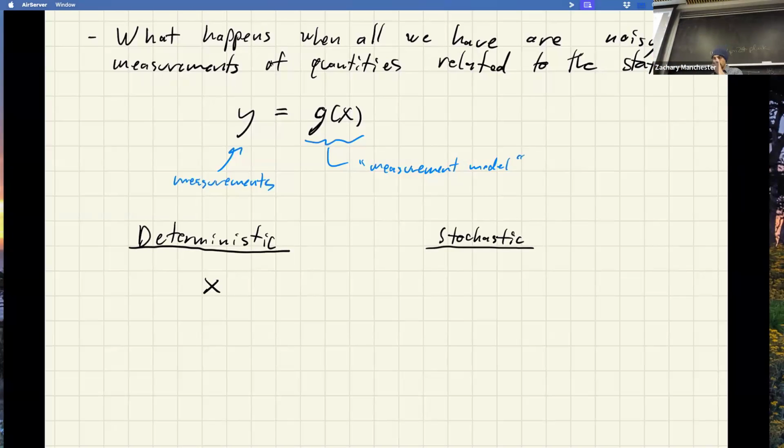What we're going to do instead of reasoning over x's is this: everything in stochastic control is reasoning over a probability distribution. It's the probability of x conditioned on y. So this is saying, I'm getting a bunch of these measurements. I know they're noisy, so they're drawn from some probability distribution. Often we assume it's additive Gaussian noise because that's mathematically convenient. And then you ask the question, what's this conditional distribution on the state given all the measurements I've seen so far?